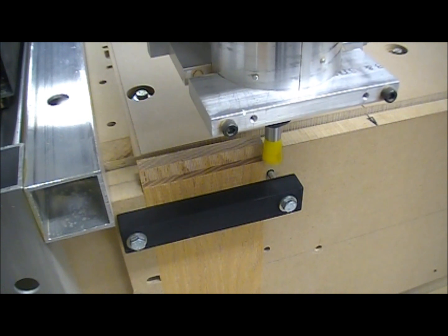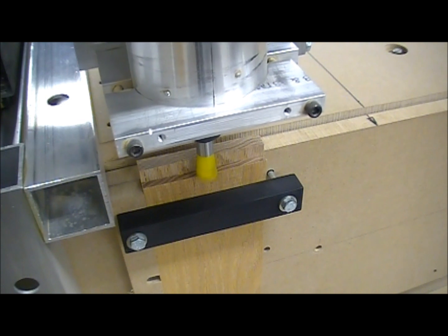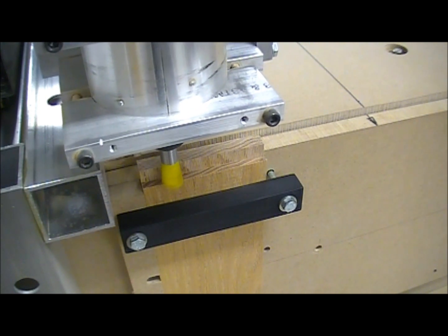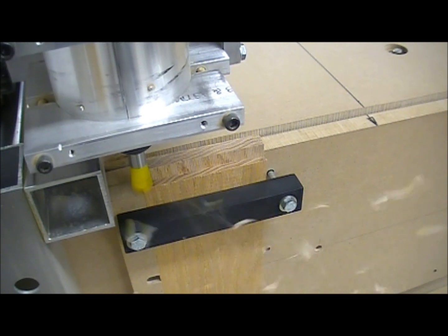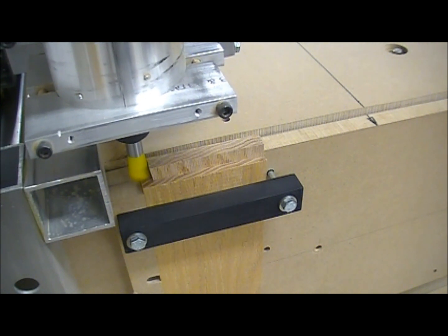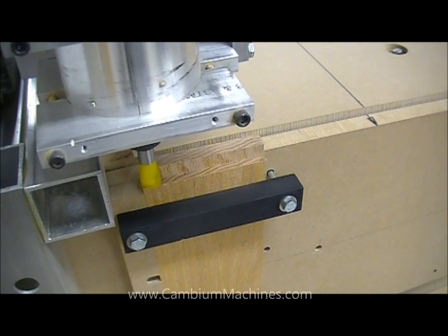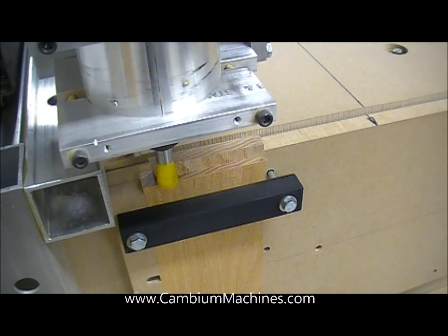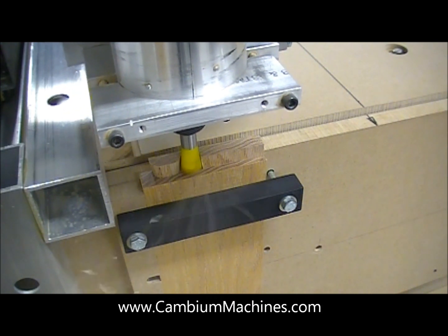If you wanted to read these existing G-code files back into Cambium code for editing in the future or modification for a related project, you could do so by using the File Open menu pick. Cambium code also comes with a set of scripts for Google SketchUp to create part models in SketchUp from the G-code files written from Cambium code. Installing and using these scripts is shown in an additional video tutorial.